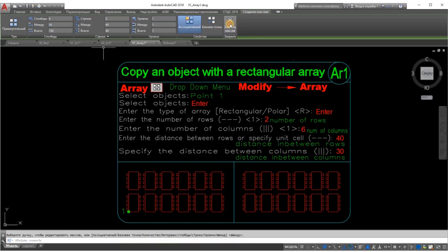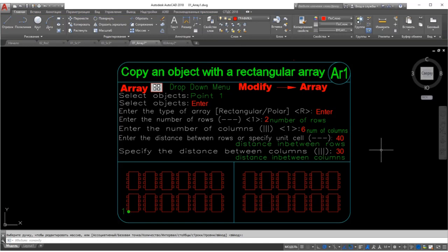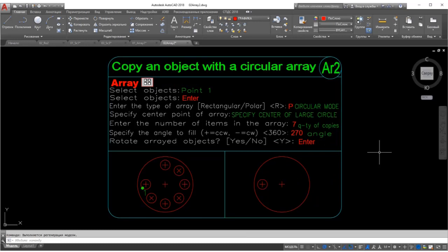First, press Escape to make sure that no command is active and no objects are selected. Second, type -array, don't forget the hyphen, and press Enter. Typing a hyphen in front of an AutoCAD command normally tells the program to run as a command line rather than a dialog box.